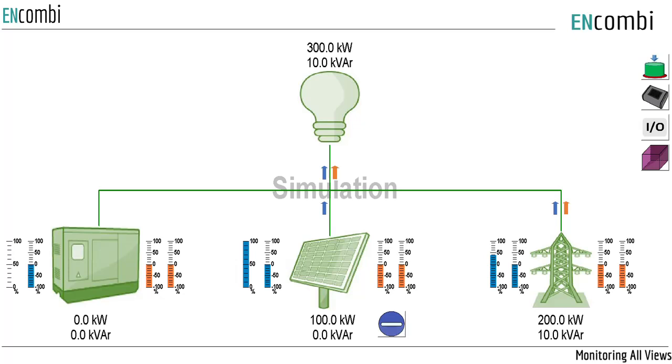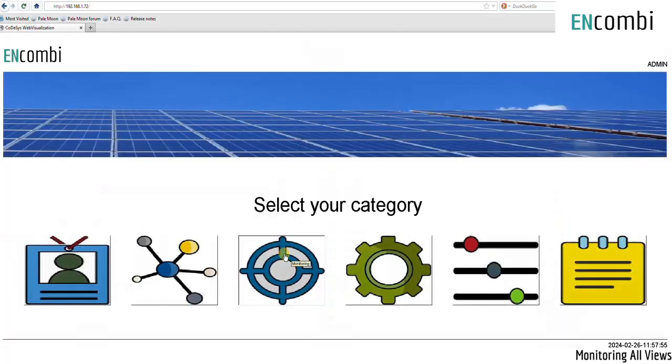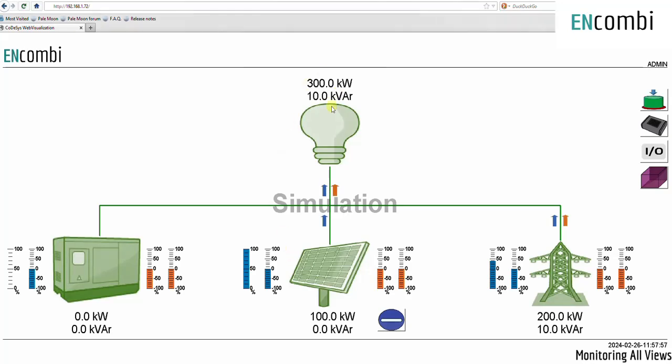Once you have completed the commissioning, you can monitor all your readings by going to the monitoring. When you click the monitoring, it leads to the monitoring tile where you will see utility connection, PV connection, genset connection, grid connection, commands panel, sensor, I/O data and simulation.